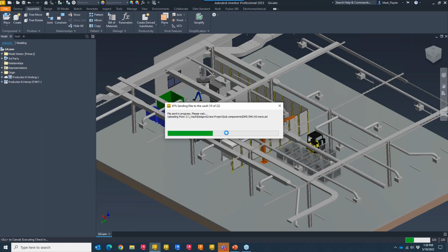I would say it's closer to a 400 level. We're starting to get mesh. We're getting connector components right now. Definitely overkill for what I want to see early on in the design process. But in the CD deliverables, it might be the level that I want to see. Okay. Level of detail changes depending on what phase we are inside of the project. Earlier in the project, the more generic massing spaces I want to see. Later in the project, as we get to final as-built drawings, we want to see a high level of detail.